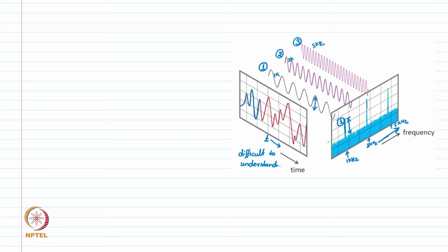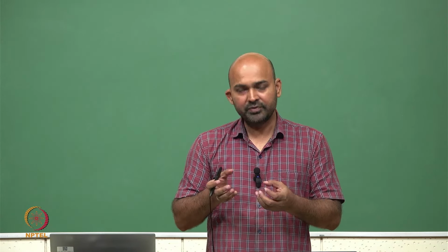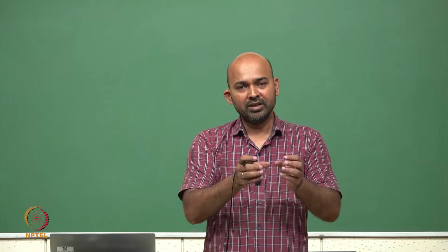So, this is what the frequency domain signal looks like, which in the time domain looks very complicated, but here in the frequency domain we know that only these three frequencies are being applied at the circuit. We can calculate the output at these three frequencies only. So, it helps us in solving the circuit. So, this is how we have a sinusoidal signal and we can convert it into a frequency domain signal, where all these components or frequencies which make up this signal will be split and plotted on a single x-axis as points.